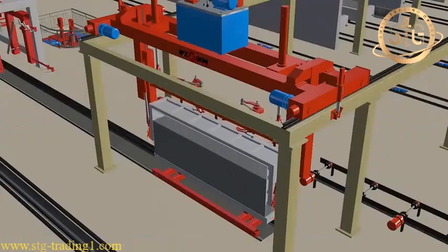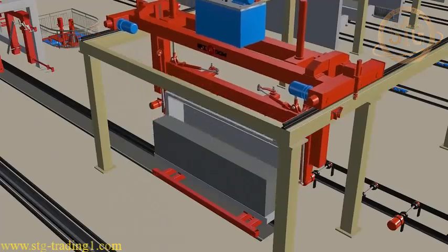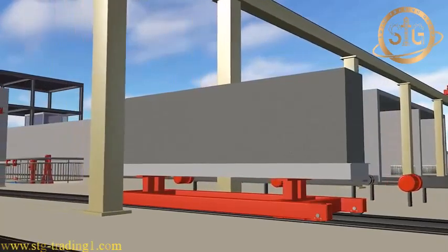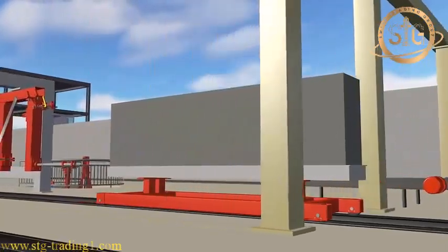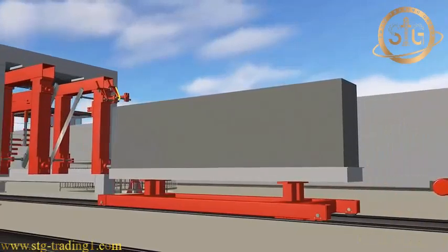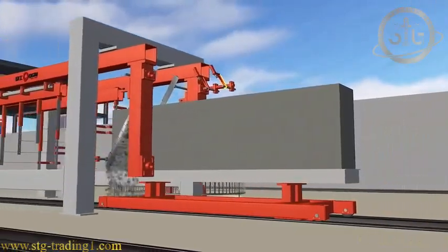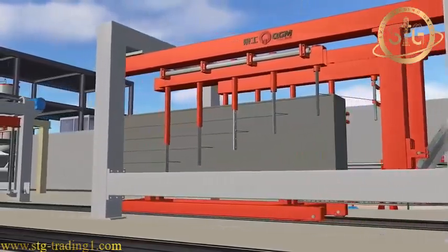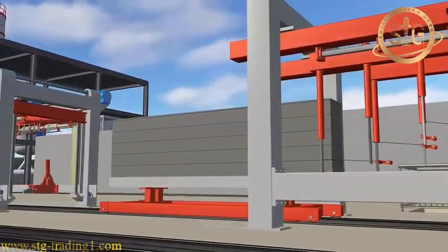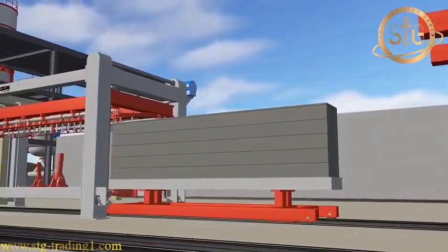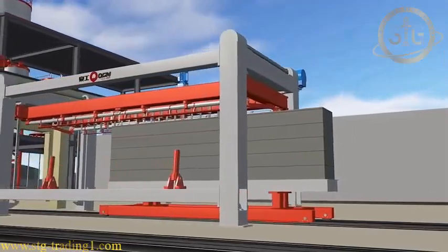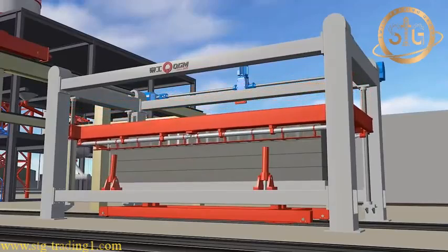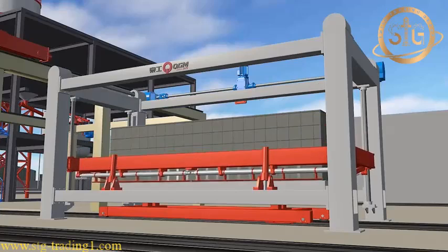Then the manipulator separates the cake from the mold. After demolding, the cakes are being cut in the cutting machine. The cutting car with the cake goes through the vertical device for vertical cutting. During this period, the thickness is being cut by the cutting blade and horizontal cutting machine. Then the transverse frame lands top down vertically and the wires swing for the cutting.